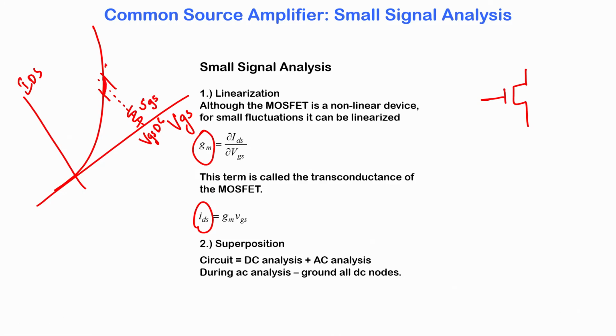It is an infinitesimally small section, and I can define my VGS fluctuating within this segment, and therefore, the slope here is constant, and that slope determines the amount of fluctuation of the AC drain to source voltage. Okay. So, in other sense, by keeping the slope here constant, we have linearized the behavior of the MOSFET. We are saying that the MOSFET is like this if I were to bias my DC voltage at that point.